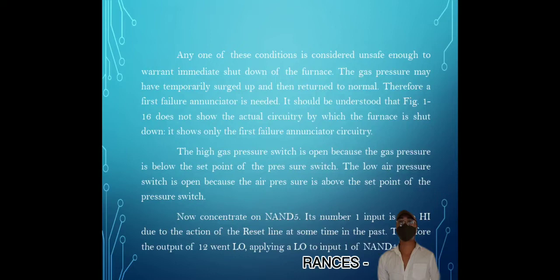Any of the conditions is unsafe enough to warrant immediate shutdown of the furnace. The gas pressure may have temporarily surged up and then returned to normal. Therefore, a first failure annunciator is needed.